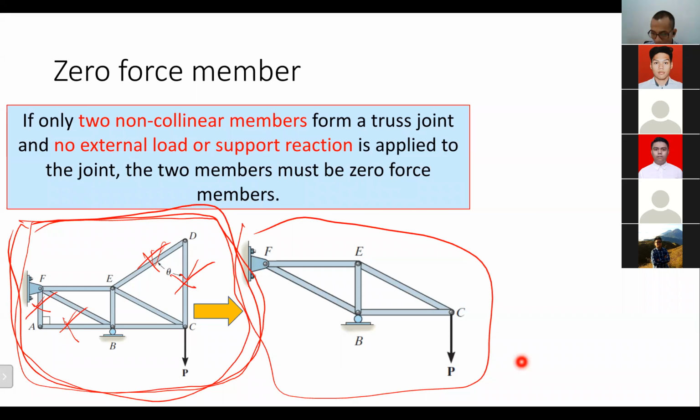Yes, sir. It will not be a zero force member if I put a force like this. If I put a force like this, for example F, like that, AF and AB will not be zero force members. And if I put a force like this, ED and DC will not be zero force members. Oh, okay, sir, I got it now.